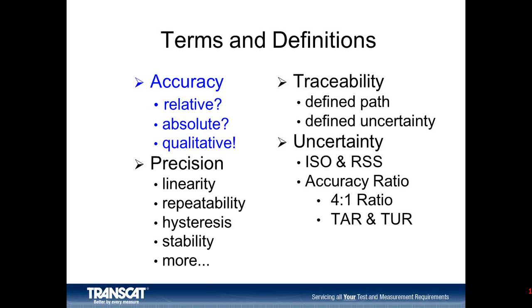In general, relative accuracy is the limitation of the performance of this device or mechanism, generally what we call performance or precision, as we'll talk about in a minute. And then the absolute accuracy, as it was used some years past, corresponds more closely to what we call today measurement uncertainty. So it can be very confusing, and when we speak in technical terms about uncertainty, we try to avoid the term accuracy except in general conversation.